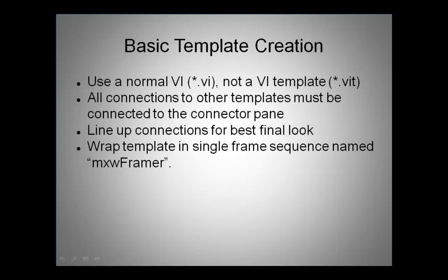Finally, wrap your entire template in a single frame sequence and name it MXW Framer. When the Codegen engine opens a template, if it sees a top-level diagram called MXW Framer object, it knows this is my template, this is what I need to do. That allows LabVIEW to do a move of the diagram of the entire object instead of doing a copy and paste of everything on the diagram.